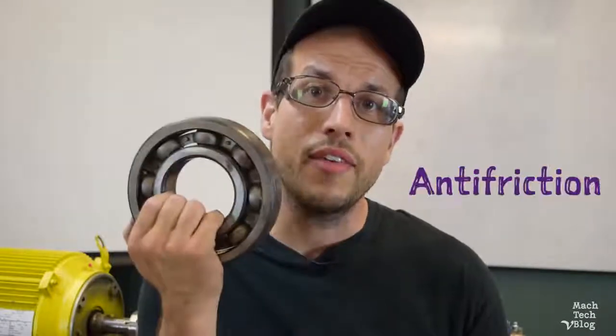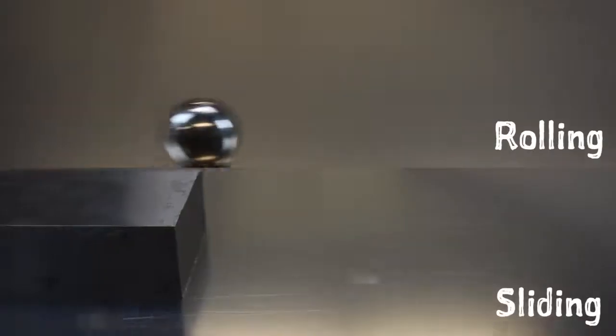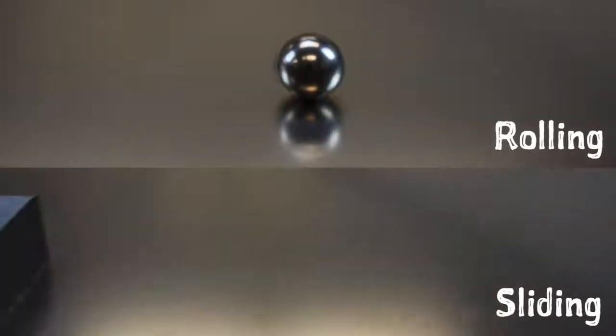Then you have the category of bearing that most people think about when they hear the word bearing, and that's the anti-friction bearing. Anti-friction bearings use rolling contact rather than sliding contact. Rolling contact has a lower coefficient of friction or drag, and that's where anti-friction bearings get their name. Now, there are enough differences between the two categories of bearing that they really deserve their own episodes. We'll deal with hydrodynamic bearings at a later date, and today we'll just focus in on the anti-friction bearings.